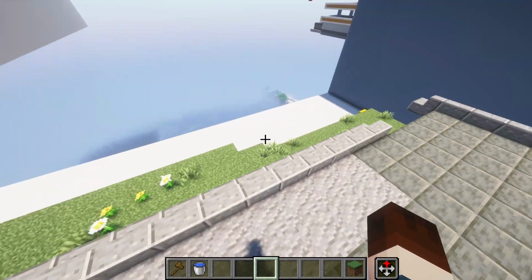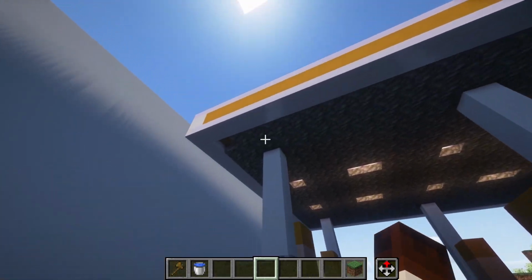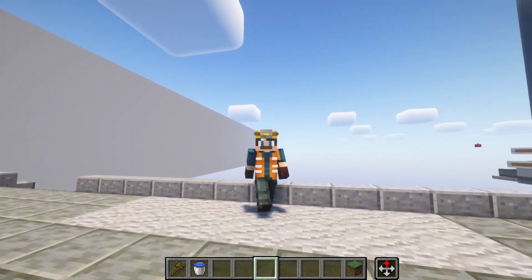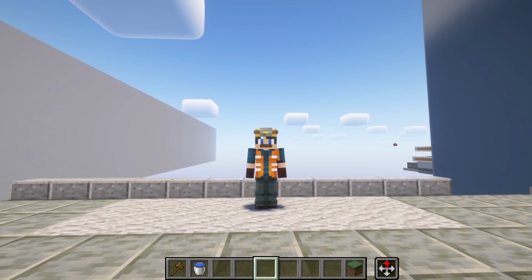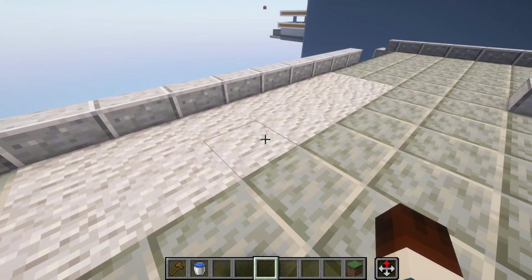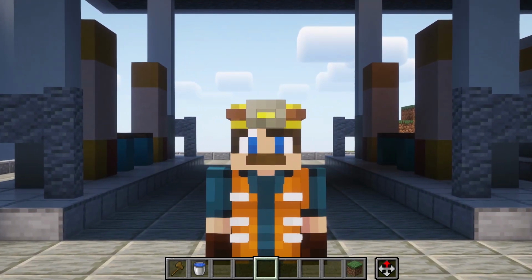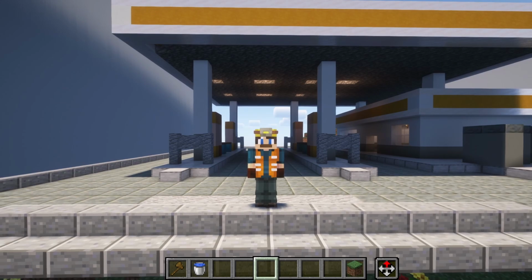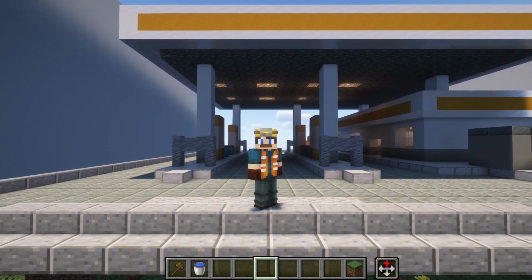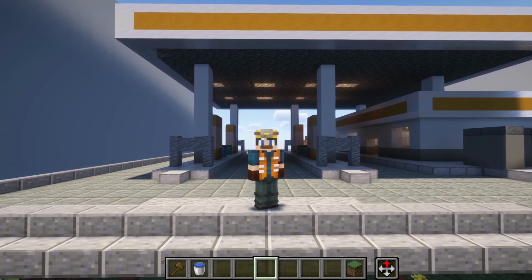And similarly, we have the permeable pavement that we used here in an example to show what it is like for the exact same feature as the green roof, although with these, it's not about aesthetic, it's just about controlling the water. Typically, this will be brick pavers or some sort of permeable pavement. They actually make asphalt and concrete that water can permeate through. Would you look at that? So by mixing permeable surface like grass and dirt and hard materials like stone, we can reduce the amount of water that becomes runoff. It's a simple, effective way to manage stormwater while our Minecraft builds look great.